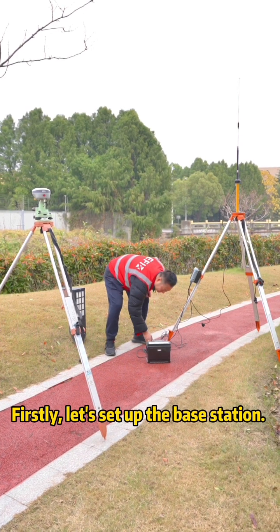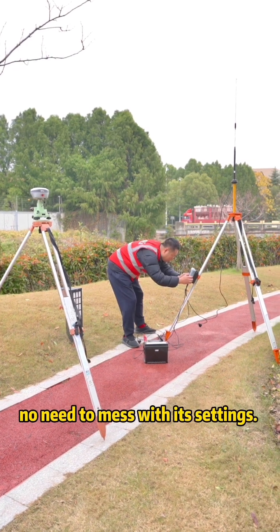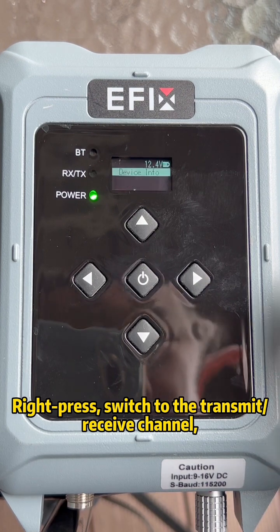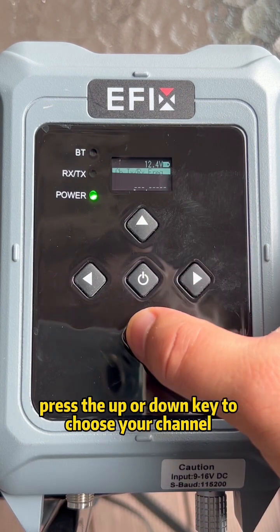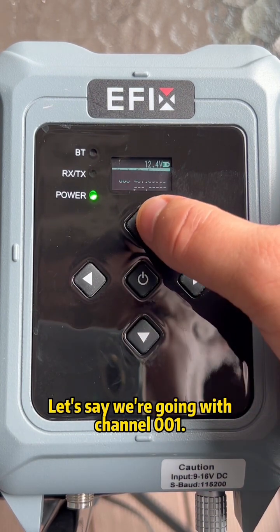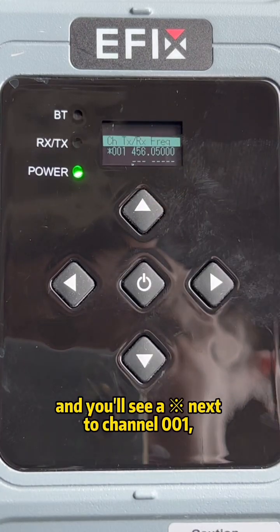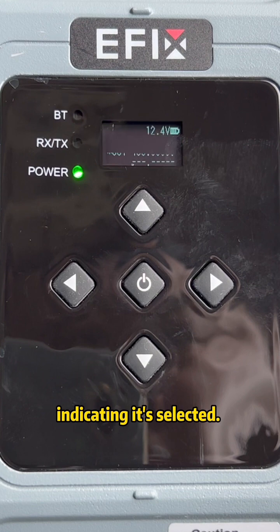Firstly, let's set up the base station. No need to mess with its settings. Just go straight to setting up the radio data link. Right press, switch to the transmit/receive channel. Press the up or down key to choose your channel. Let's say we're going with channel 1. Press the power key to confirm, and you'll see an asterisk next to channel 1, indicating it's selected.